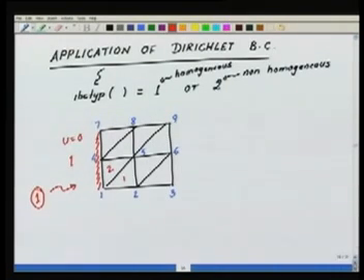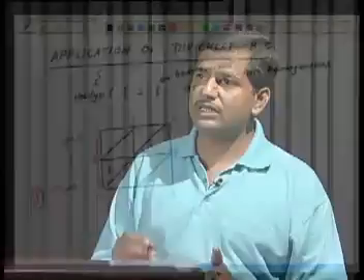IBC type should be 1. Okay. So here, as soon as I do that, I find that this is an edge on which the Dirichlet boundary conditions have to be applied. So as I loop over the elements to find the neighbors, after making the mesh, immediately I can also make a list of the degrees of freedom which are lying on the boundary.